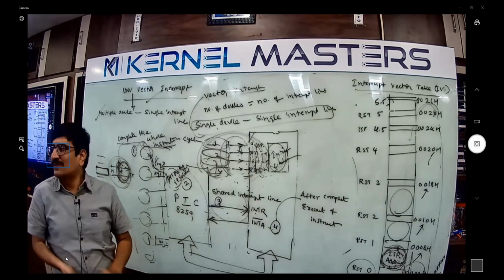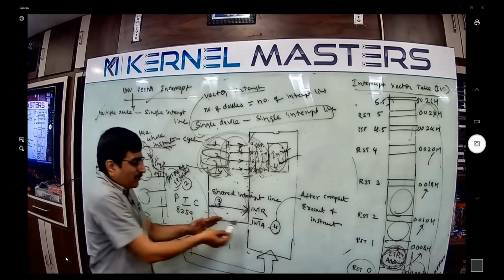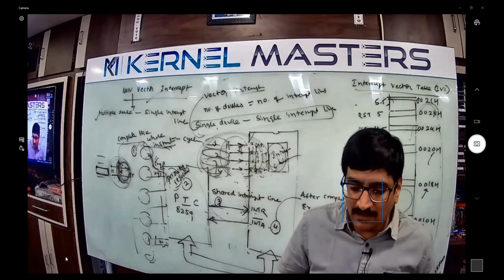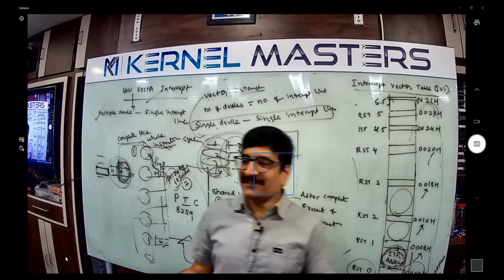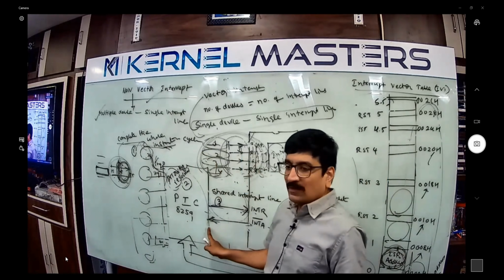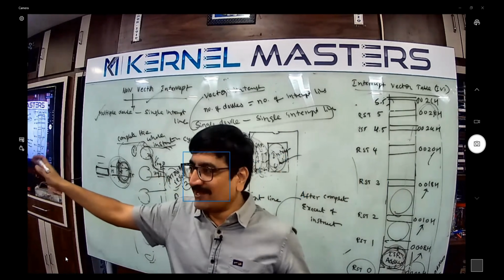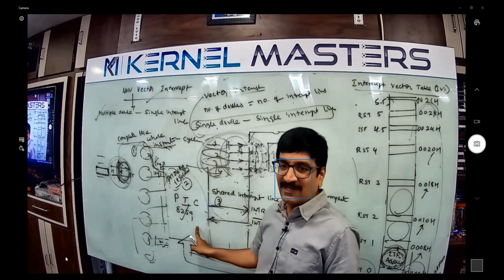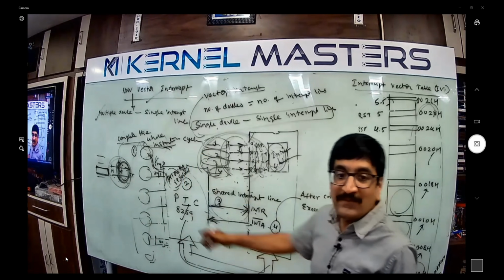That's why it gives the acknowledgement. The microprocessor knows an interrupt occurred and is ready to handle it, but it doesn't know which interrupt or where to go. It doesn't know the path. So the acknowledgement tells the PIC that the microprocessor is ready to handle the interrupt but doesn't know where to go. Whenever the PIC receives the acknowledgement signal, it immediately sends the interrupt vector address.